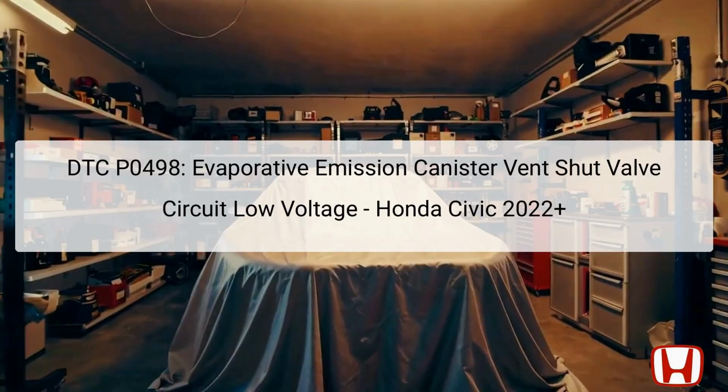DTC P0498 indicates a low voltage condition in the Evaporative Emission Control System, specifically relating to the Canister Vent Shut Valve, CVSV. The CVSV plays a crucial role in controlling the venting of evaporative emissions from the fuel system, directing vapors into the intake system for combustion.